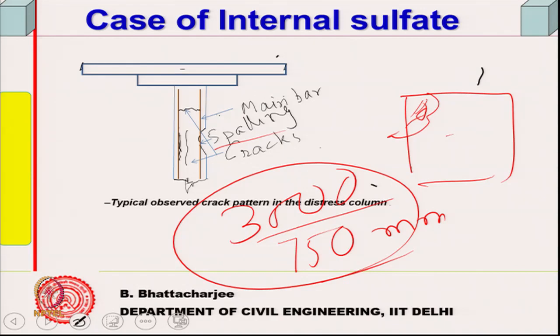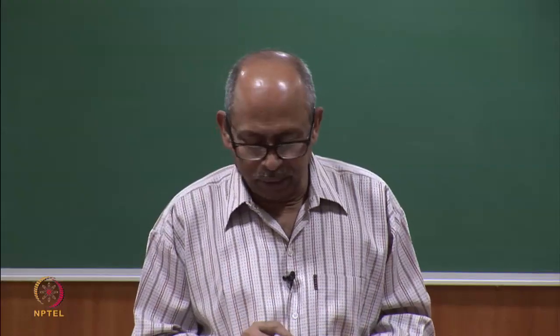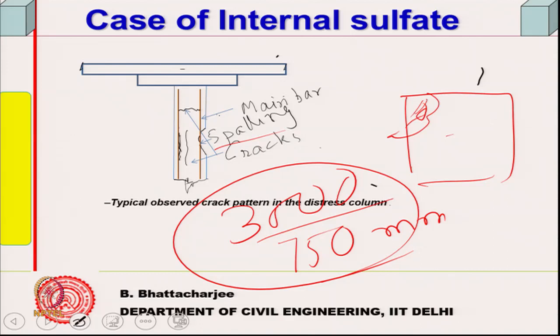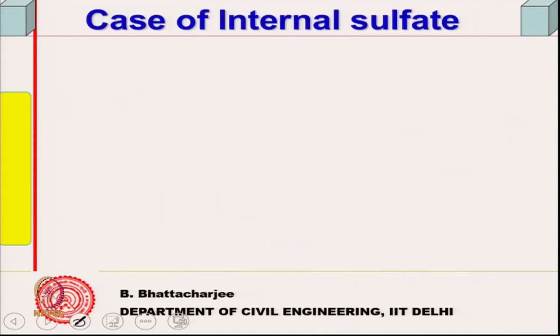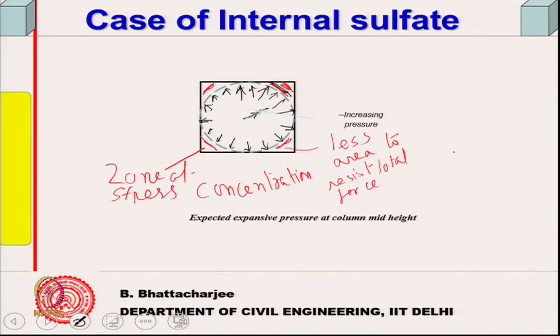In 8 months old concrete, it is not possible to have rebar corrosion or a similar sort of thing. So, then, there are horizontal cracks also, and especially in the corner. Now, visualizing this stress pattern, what I thought was that there must be a crack pattern, so this concrete spalled off because there will be stress concentration there.